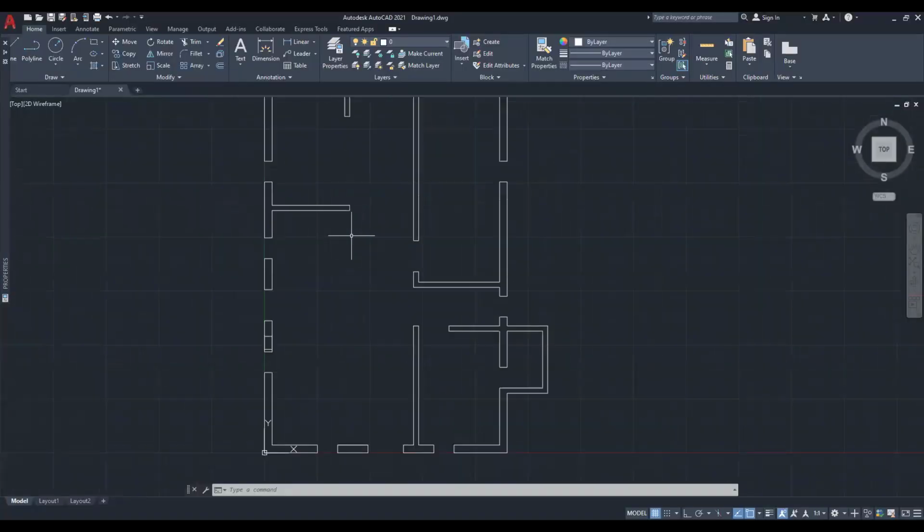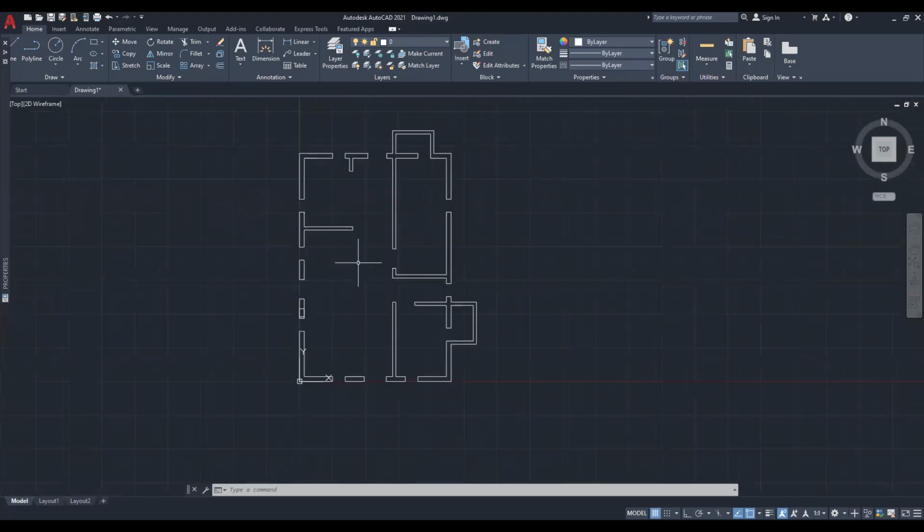With the help of one plugin, Paste from AutoCAD, I'll show how I do the copy. I'm selecting the whole plan here and using Control C to copy. On our keyboard, I can directly use Control C to copy. Then after copying this, I'm going to SketchUp now.